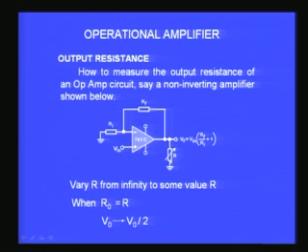Then what I do, I introduce this resistance and vary the value of the resistance by using the potentiometer knob until I get a voltage which is half of what I measured with no resistance present here, that means with infinite resistance. So, if I get half of that value, then I would say the value of the R that I measure here now is the output resistance of the amplifier. This similar situation we have already discussed with reference to the input resistance last lecture.